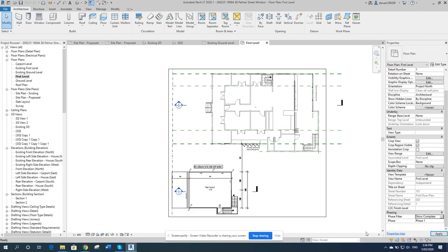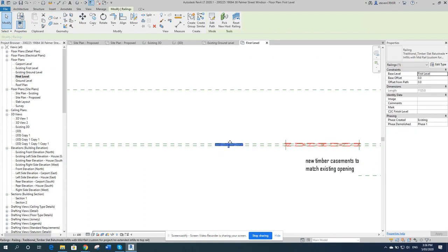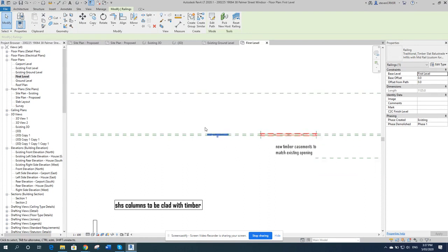So you can go show complete, which just makes it a lot darker. If I go previous and new, it lightens the sections that we're not dealing with and brings these forward. It puts these, say, at a half scale, so people are more concentrated on this. On this one there wasn't much demolition, but you could go in and go show demo only, and we can see that we demolished some handrail in here to start with, and we demolished the existing windows because they were going to replace those.